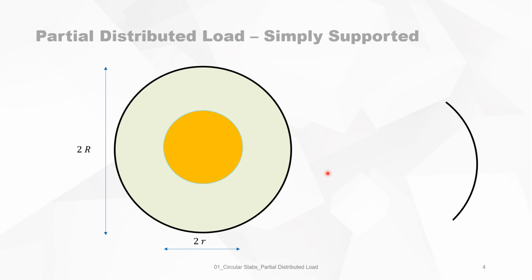Now we will use the yield line method, and for this we are looking first for the axis of rotation. So I take one part of the slab, and the axis of rotation is in a point on the circumference of the slab, because I want to make a mechanism of pieces of slab moving around a rotation axis. So it means it's a line like this on each point.